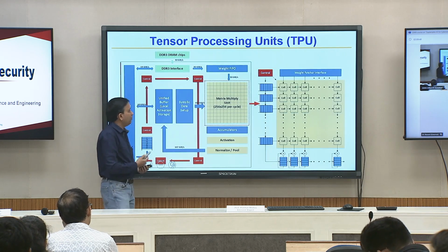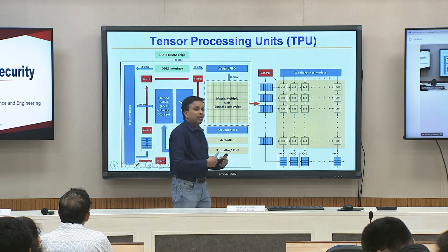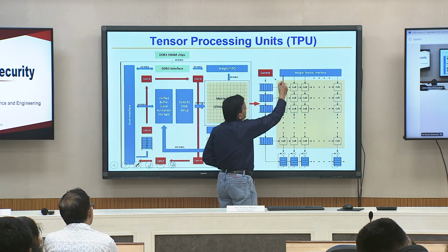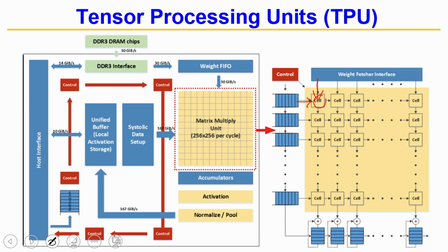The way the idea works, a systolic array, instead of spending time telling you an architecture course: if some input comes in here and you compute something, that computation would be used by this cell as well as this cell at the next time step. When this cell is done, it is going to provide this cell and this cell. When this cell is done, it is going to provide this cell and this cell.